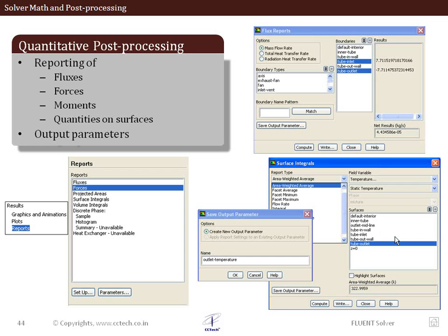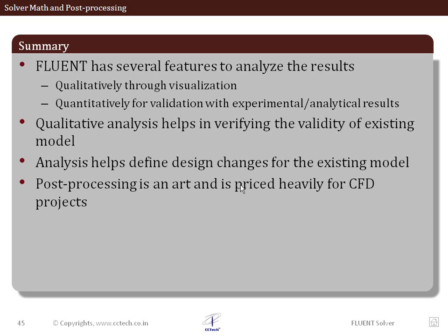All these quantities can be either displayed on the screen in the terminal emulator, or we can also create an output parameter which can then be accessed in the Workbench. So Fluent offers a variety of options to do quantitative post-processing, either as a standalone entity as well as integrated within ANSYS Workbench. Just to summarize, ANSYS Fluent has several features to analyze the results qualitatively as well as